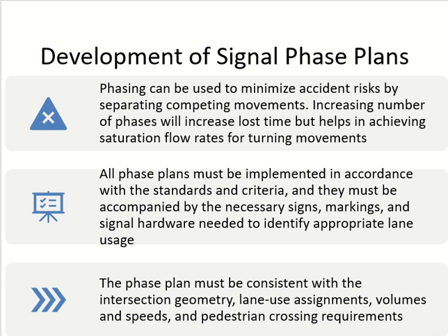What do I have to do at this approach? Which control device? Like arrows. So you need lane markings with arrows, right? Okay. Anything else? You need a separate lane. You cannot have a lane which has straight and left both. You cannot have a shared lane. Okay. Anything else?